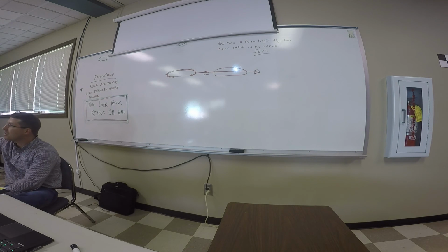On an ALTA survey, we're just looking to get a single location shot of it. Yeah, a single shot on that thing, we're going to draw it. And just maybe tell us what it is, maybe a 4 by 4 weir. One shot, preferably on the top of it, but don't waste time climbing up on top of a weir if you can lean the rod over there and get it, and just maybe put -NE on it so we know that the elevation can't be used.